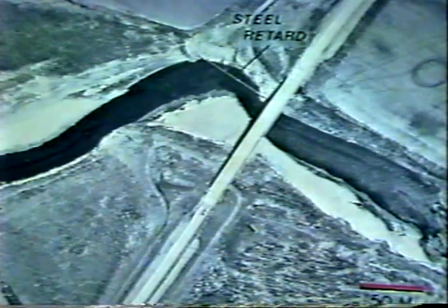Spur dikes have been generally successful for control of overbank flow where it enters the bridge waterway, and no dissatisfaction was found with the curved shape in general use. Where spur dikes are used for control of channel alignment, the curved shape is not necessarily advantageous. Many bridges have resisted flood forces for a long time without the use of countermeasures.